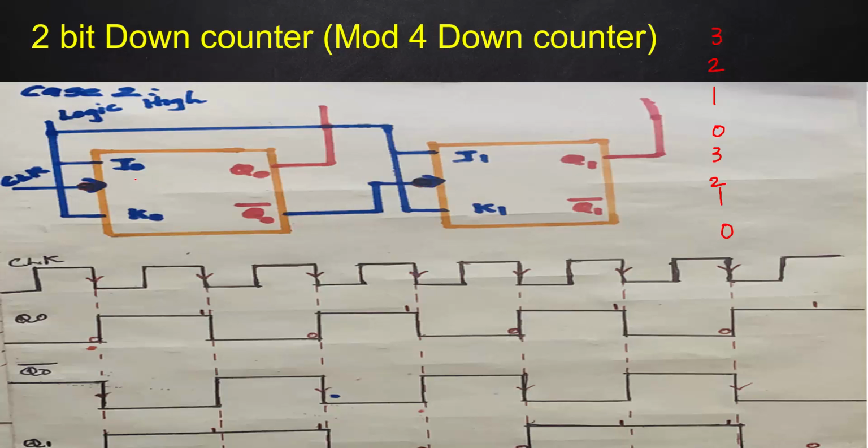All others are the same. We need to keep both J and K high, and the first one is connected with the external clock pulse. Instead of connecting Q as clock to the next, here we need to take Q bar of the first flip-flop as clock to the next. Then it will act as a down counter.